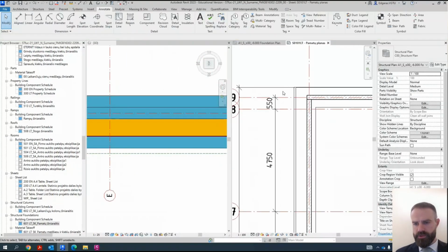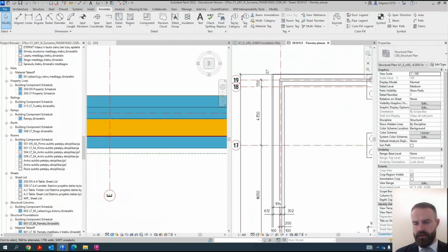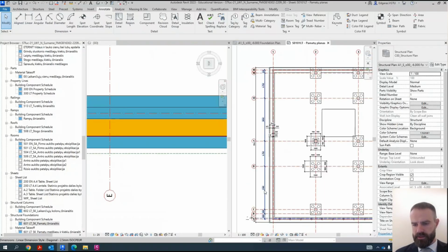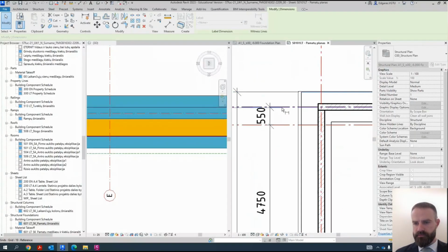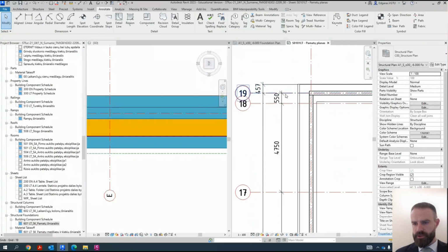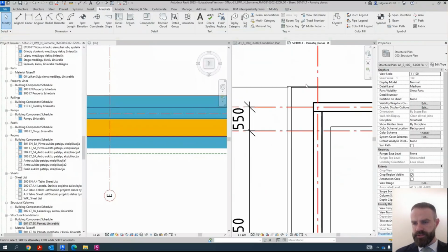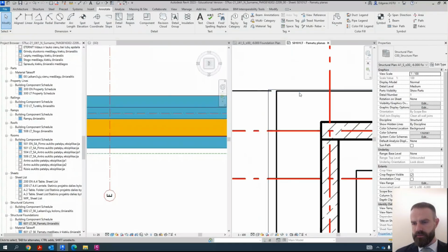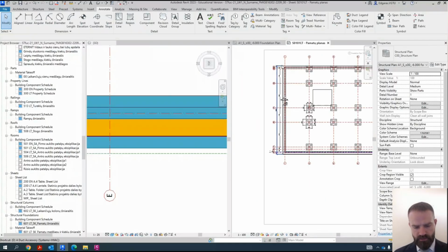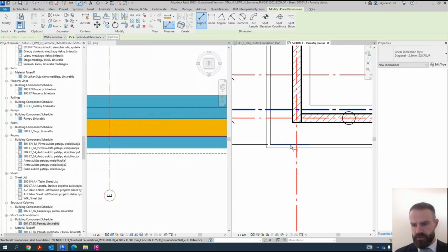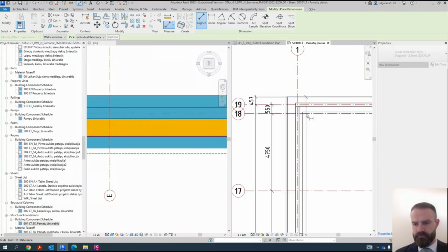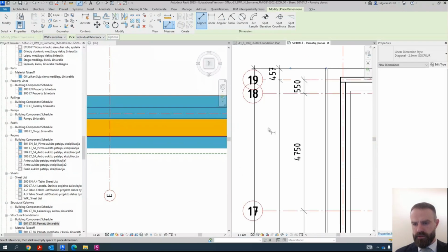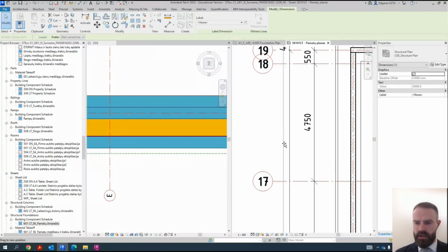Now my dimension was hidden because one of my lines was outside, and now I can just move and put dimension. So it shows the distance to the far side of objects, and the last one shows all the size of the object. And normally Revit should grab and snap the distance.